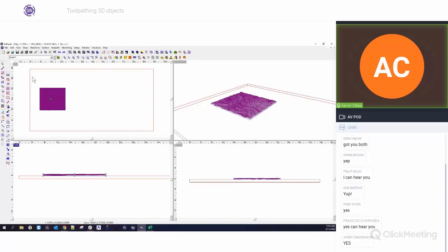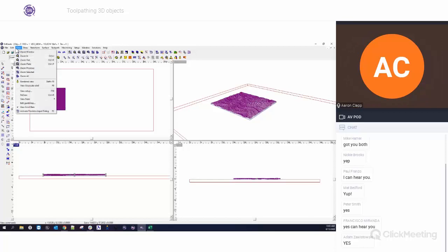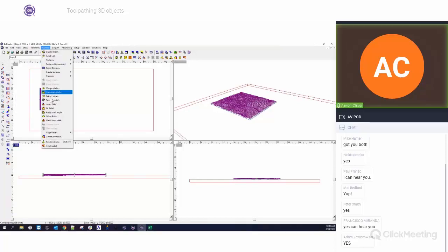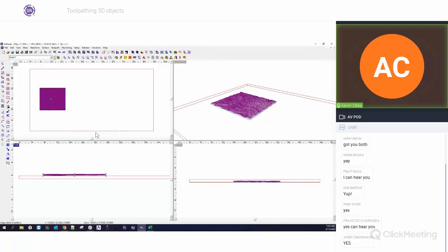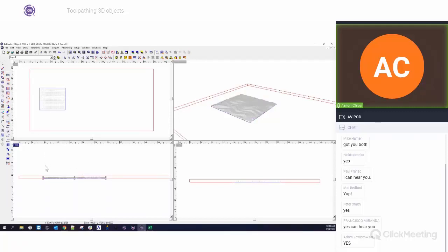But a lot of times, and this is why we say to move things before, if we go to Surface, Align Reliefs, and align the relief to the bottom of the plate, sometimes, and not in all cases, it's kind of hit and miss, this toolpath will not go with the object. A lot of it depends on whether you're doing some masking and other things along with that to go with this particular object.